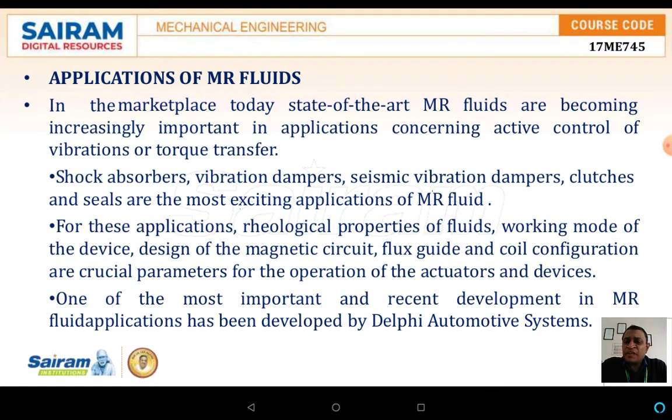The application with respect to the MR fluids, as we know, the ER fluids as well as the MR fluids have major applications in clutches, dampers, or braking systems, where power transmission is taking place between two members, or if you want to bring the system to rest. They can also be used as vibration absorbers, either passive or active control vibration absorbers, or as torque transformers or transfers.